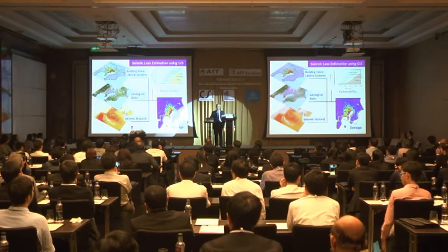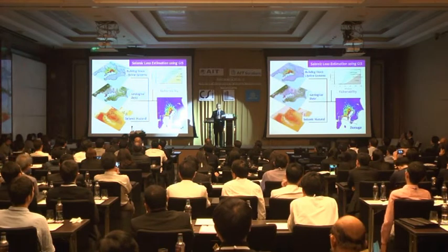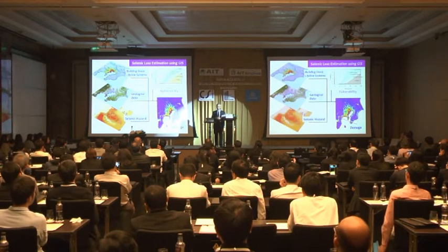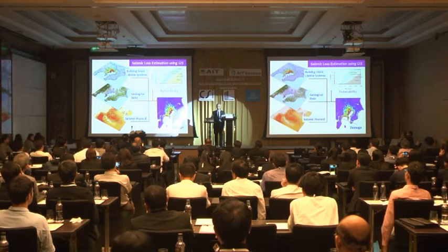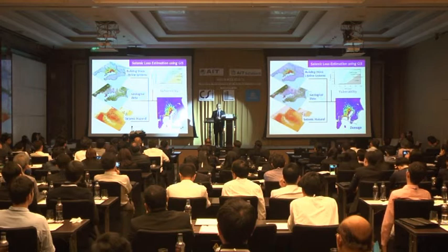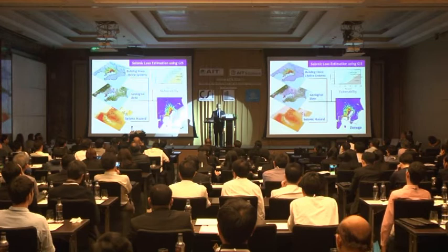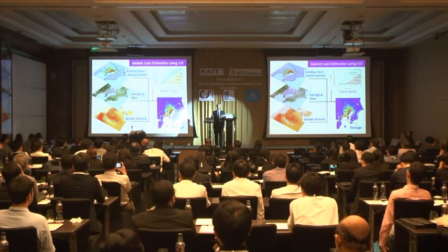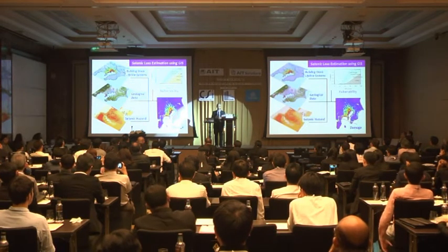If we have information about seismic hazard and we combine it with information about geological data like soil condition, basin, combined with the information about building stock, infrastructure, lifeline, transportation system, if we combine this in the right way, we will be able to estimate the damage or loss created by earthquake for any city or any town or any area. This is called seismic loss estimation.